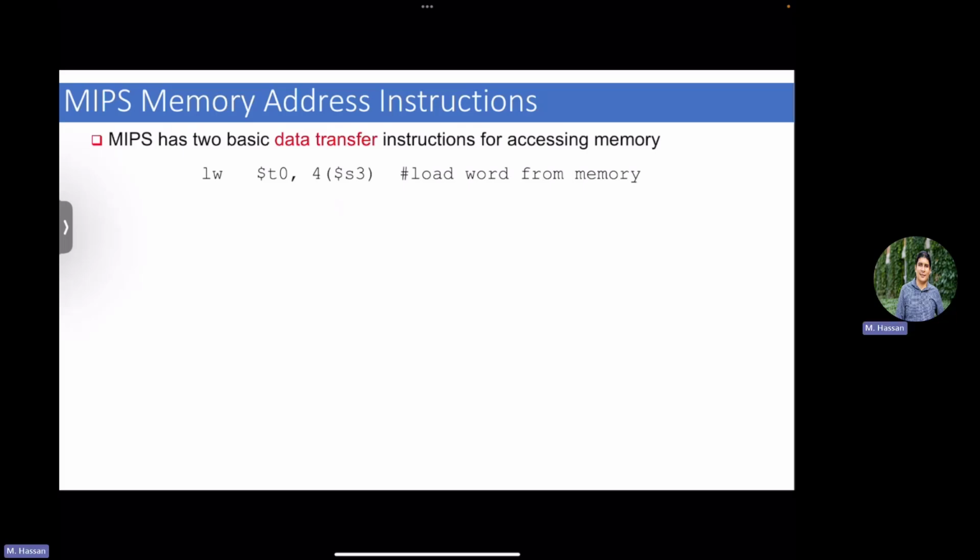Reading from it, right? So loading is in fact loading from the memory. Loading means you read from the memory and write to a register. Store means you take a register and write it to the memory. Good. The load is a memory read request. A store is a memory write request. That's very important for understanding how the architecture really works for load and store.